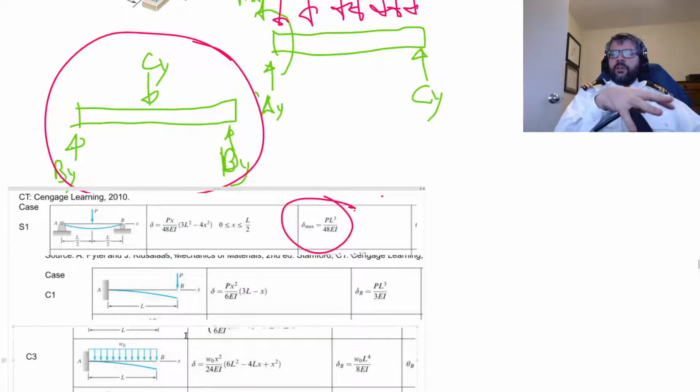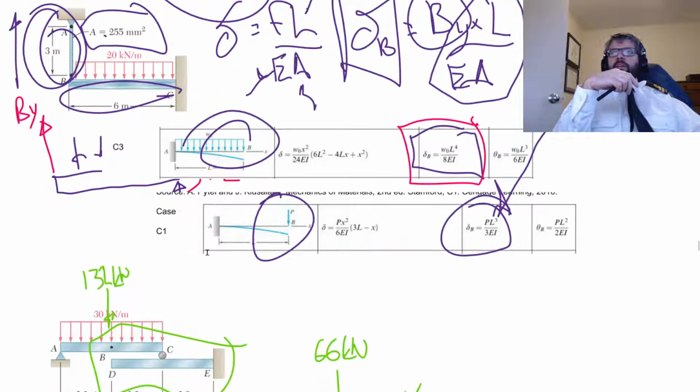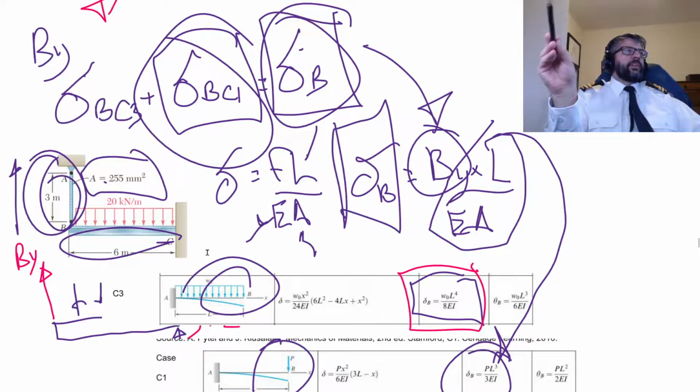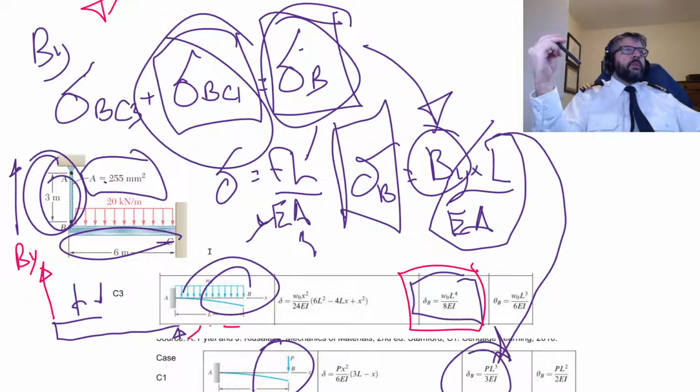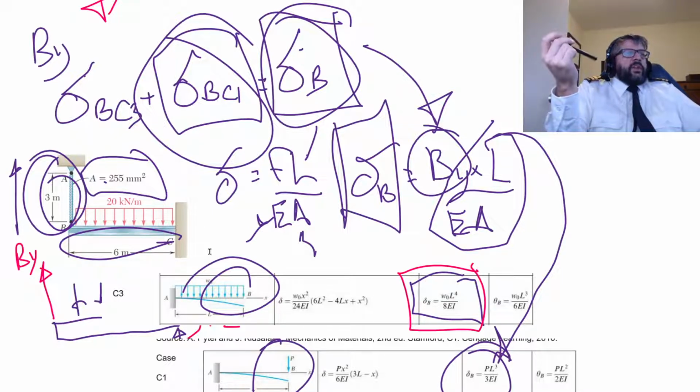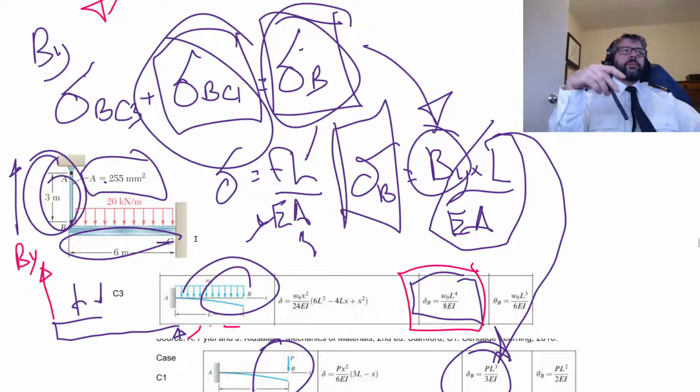So basically, that's exactly the same idea as what we saw up here. It's just that the thing that's acting as a spring, where the force is proportional to the total displacement at the end of the cantilever beam, it's not a spring, it's not a rod, it's this other beam. But same principle applies. Formulas are going to end up very similar.